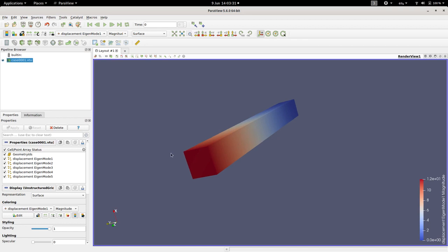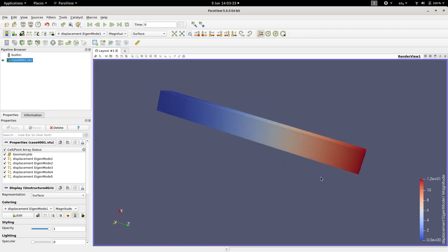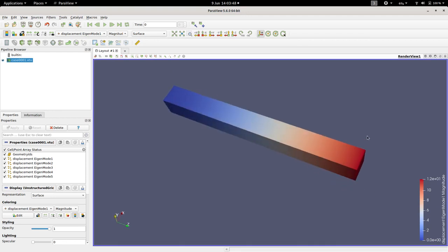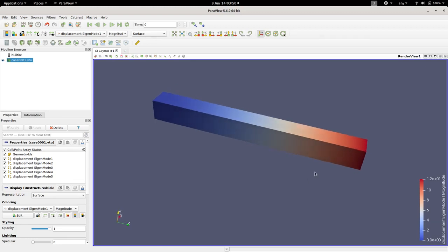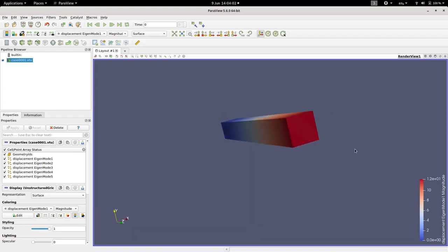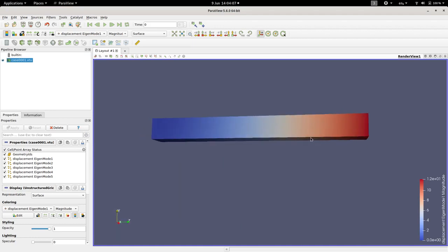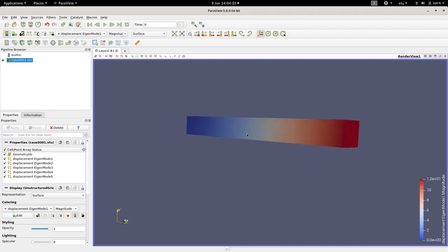So what is normally done with these eigenfunctions is to normalize them so that they go from 0 to 1, and then at steady state, if there is a forcing factor, for example, some sine wave force applied over here, the response of the bar will be a sum of all of the eigenmodes, of all of the eigenfunctions, with certain coefficients that depend on the boundary conditions and the forcing factor.